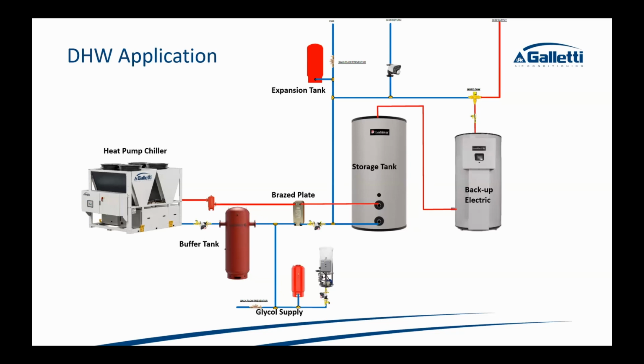Well, that's great if we're in the South, where you're heating the water in the unit and sending it directly to a storage tank. But if you're up north and you're glycoling that circuit, then you have a double wall heat exchanger with an air gap. You're reducing the ability to transfer heat, right? The thicker the plate is, and an air gap is an insulator, all of those things will knock the heat pump down in efficiency.